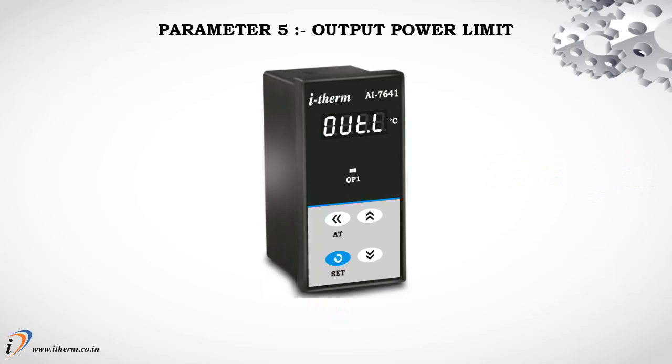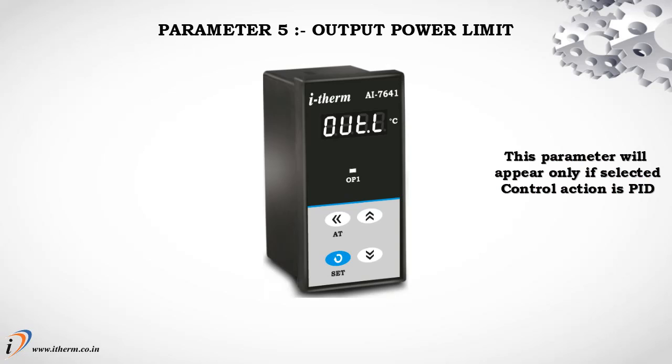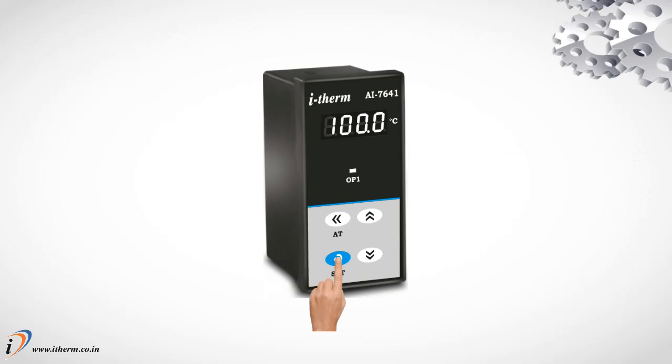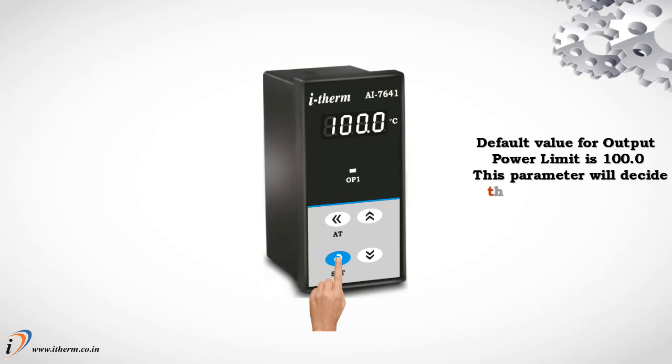Parameter 5, output power limit. This parameter will appear only if the selected control action is PID. Default value for output power limit is 100.0. This parameter will decide the maximum output power in percent applied to the load.